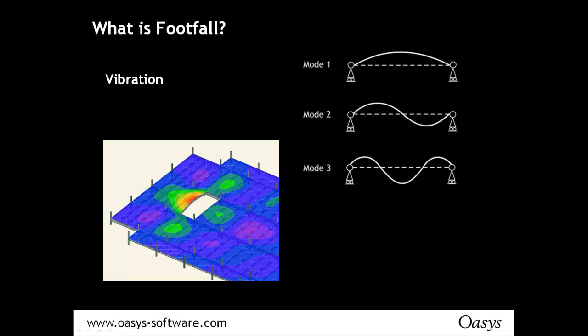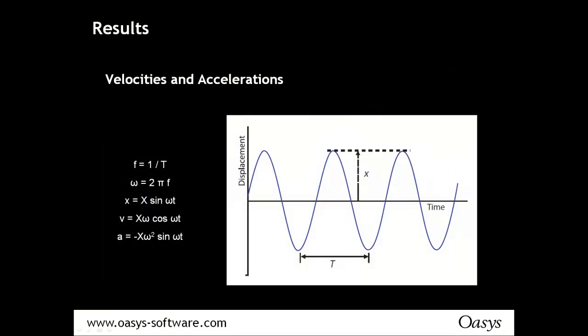Now, once you have the vibration modes, you then need to do a subsequent analysis to calculate the velocities, accelerations and response values of the floor.